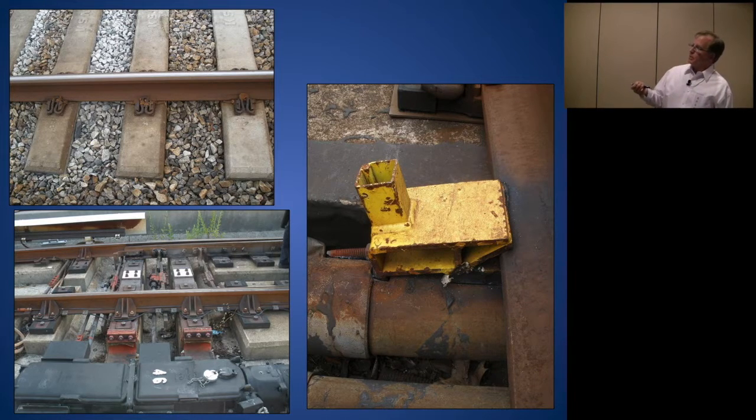There's that switch again. Any one of those insulators can go bad. This is tie and ballast track. If you look right here, I don't know if you can see that well or not. There's supposed to be little insulated white nose pieces on those fasteners there. They're all busted up and gone.